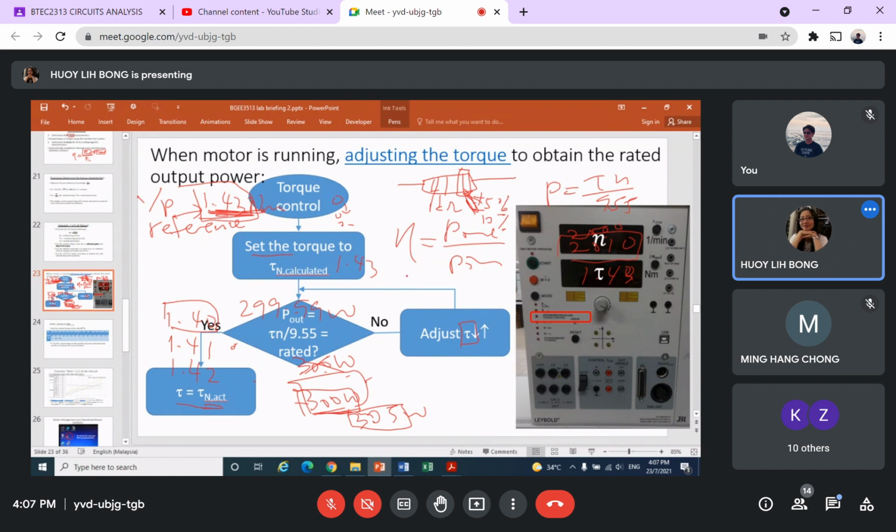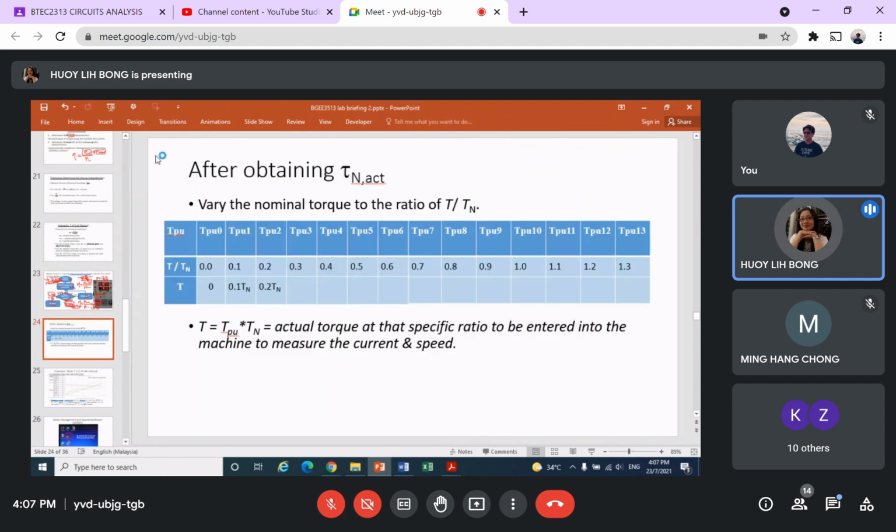But for this, you only get 1 point, which is V times I. I measure the voltage, I measure the current, and then I measure torque and speed. Then I get efficiency. Yay, done. Finish experiment. Correct? But doing this, you only get one result.